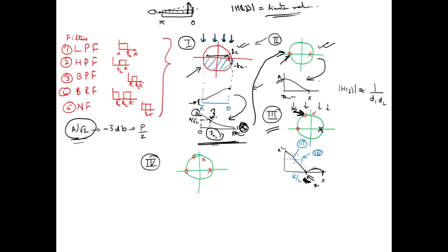So to meet the condition of a realizable filter, we should add another pole onto the existing pole. So at this location, we will be having two poles. Okay, are you getting my point? Now, since we will be having two poles, the system becomes realizable.